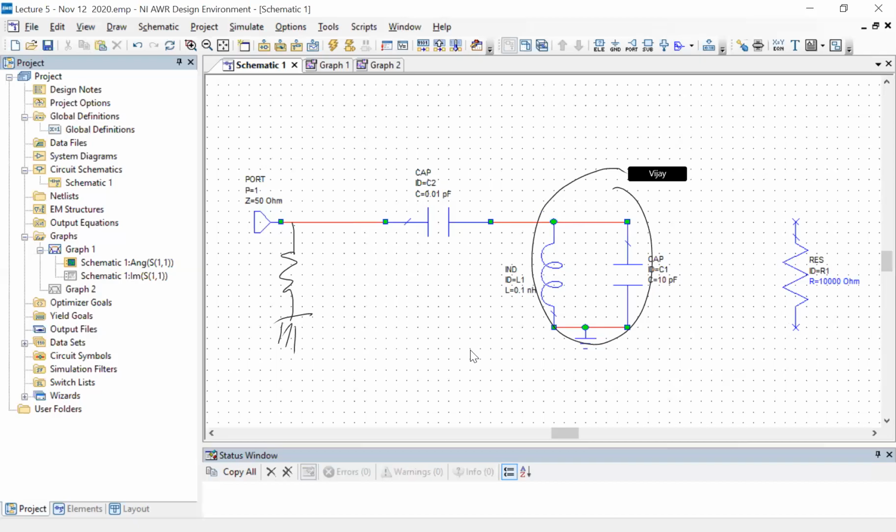Why? Because any voltage which is here, so remember last time we had discussed that the voltage across this, if you call that V, then the power dissipated is basically going to be V squared over 50, which is the 50 ohm. So that is the amount of power being dissipated. This is of course for AC signals, so we are talking about some average over a cycle, RMS and that kind of stuff.